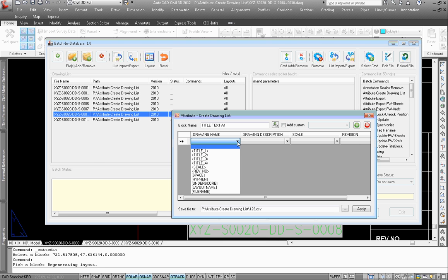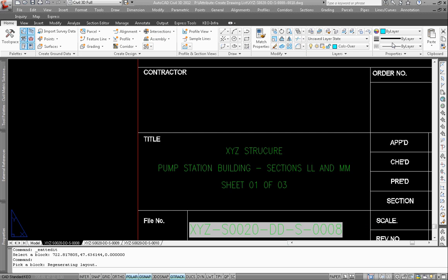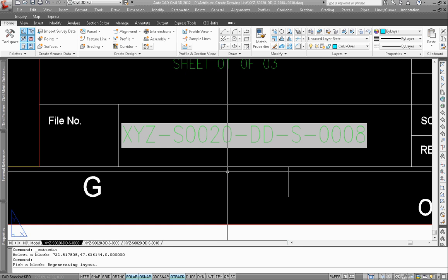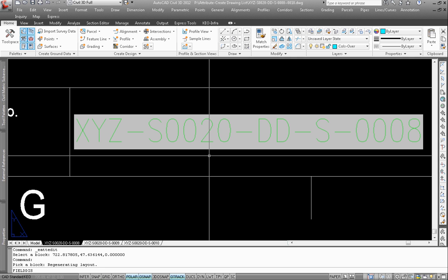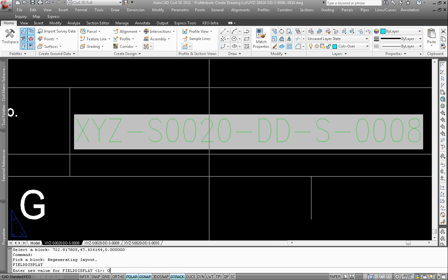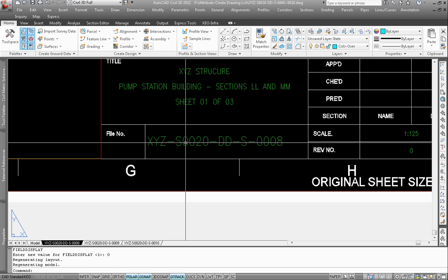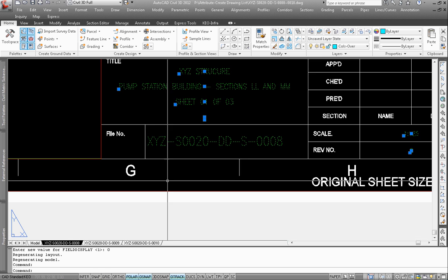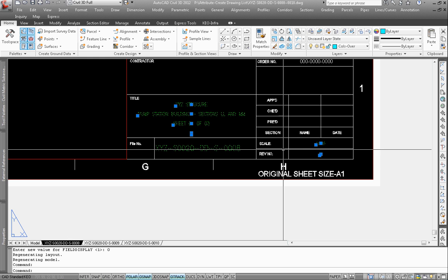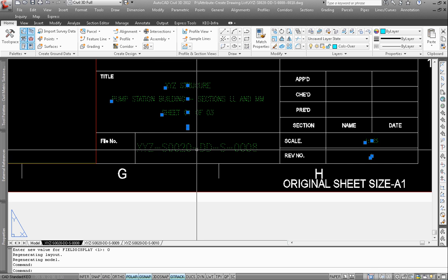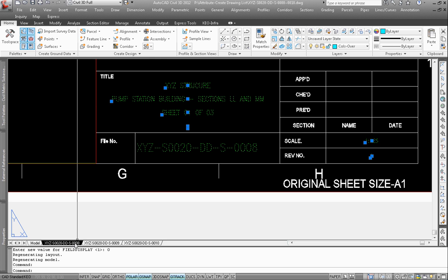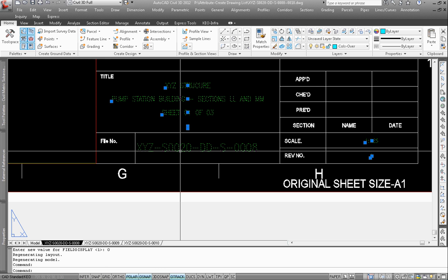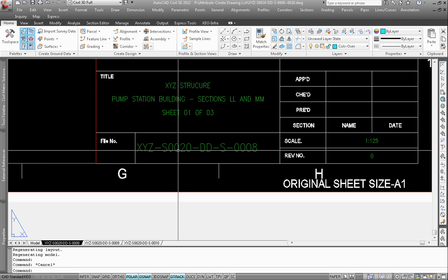In the drawing name, let me close this. Minimize. Okay, so you can see here the drawing name. What they have taken is not clear. Let me field display 0. Okay, so it reads from the current tab information. You can see all those things are attributes, plus they have added a text field which reads automatically based on the layout tab name here. So it's not coming in the attribute. You cannot export this information.